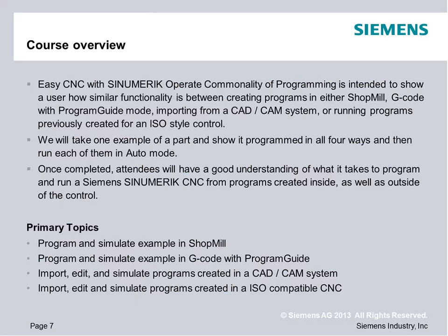Then we're going to look at it programmed through ProgramGuide or our Siemens-style G-code. Then we're going to import a program that was previously posted from a CAD/CAM system, and then do the same thing, importing something that was created for an ISO type of protocol, traditionally more like FANUC-style programming. All 4 programs are the same job, so it's all identical.